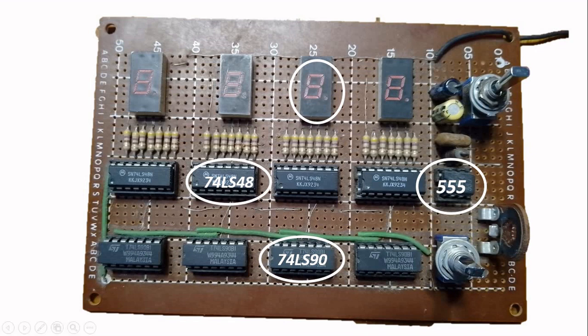So the way I did it is I built this PCB from a 555 as a pulse generator. Then I have some counters, and the counter has output as BCD. It goes into BCD to 7 segment. So as you can see on the card here, you have a potentiometer, so I can play a little bit with my pulse widths and set how many pulses I have in a second. So the idea is not having 80 pulses, but I need to have more than 1000 pulses, so I can capture as accurately as I can from my relay.